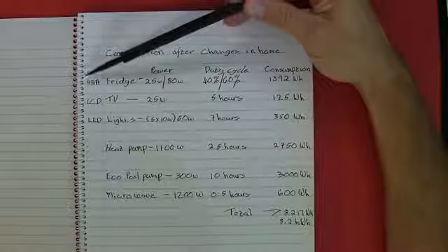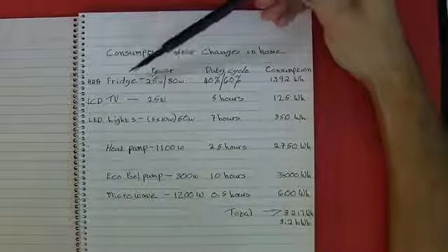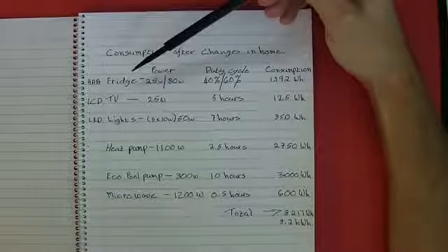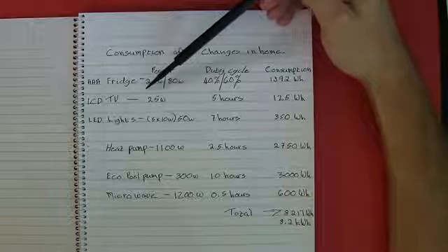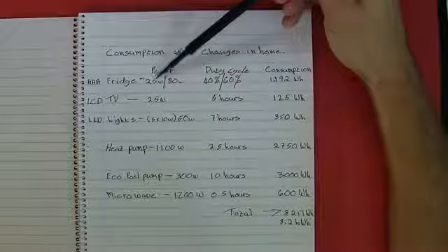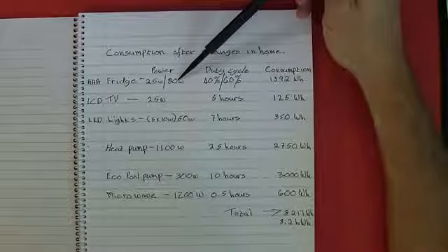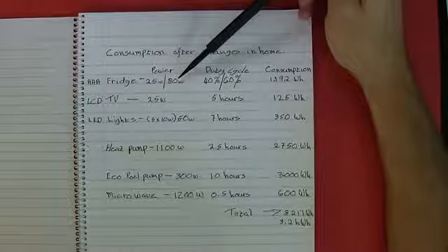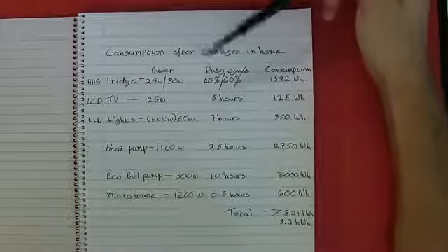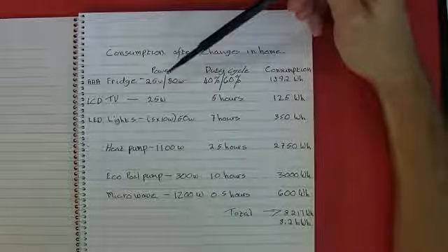They have a rating to say how efficient they are, AA or AAA, and that means they have motors that run more efficiently. They also have better insulation, which means they don't have to switch on as frequently. So you've got a double saving there. The low running power could be dropped to 25 watts. Its running power when it's actually circulating refrigerant with a motor could be dropped as low as 80 watts. And then the duty cycle can be reduced because the insulation is better on a fridge like this, so it's kept colder.